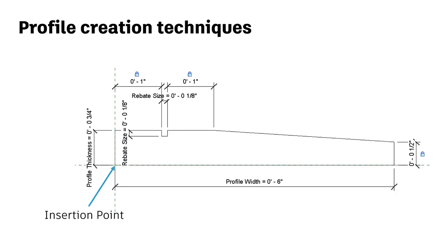A profile family has two reference planes in the default template which defines the origin or insertion point. When the profile is used within a project, the profile can be flipped, rotated and offset. However, you should consider the most appropriate point for insertion.